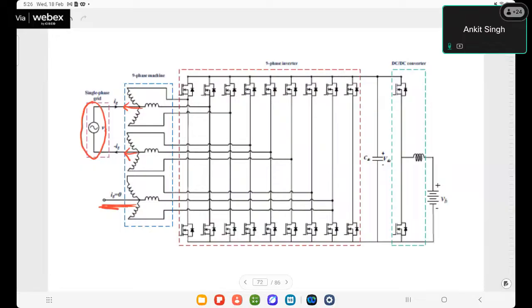the different topologies or different converter configurations in electric vehicle onboard charging. So neutral point assessment is another parameter, because here we are connecting either in a three-phase system or in a single phase system, so we are accessing the neutral point also. The neutral point should be available for the connection of the grid supply during the charging.